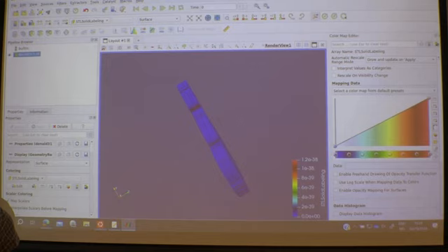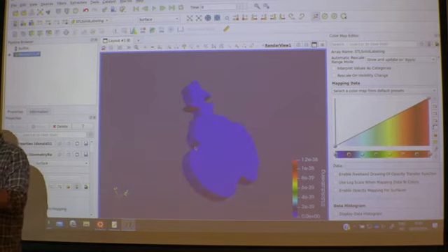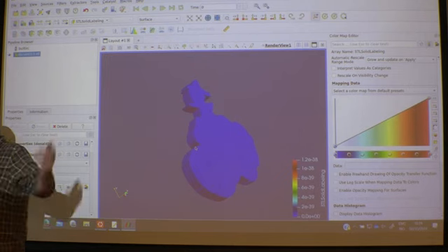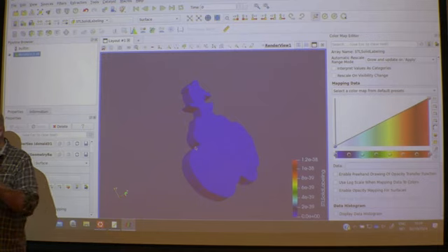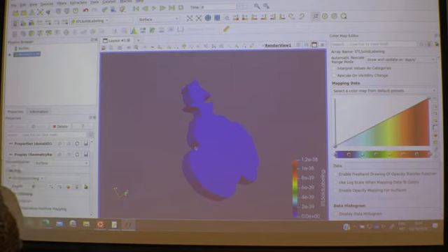Because if you put it outside, then it starts meshing from, say, the end surface here, the front and the back, to inside that meshing. And you get additional cells, which in the end you're not going to need anyway, because we're going to extract it down to a 2D case. So keep your background mesh very narrow in the Z direction.